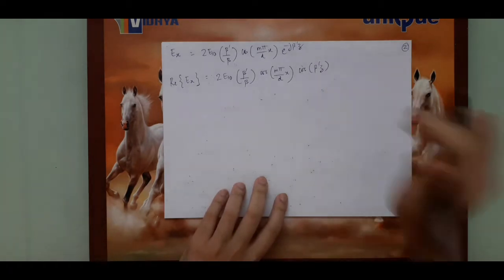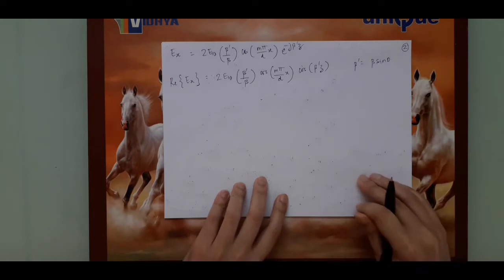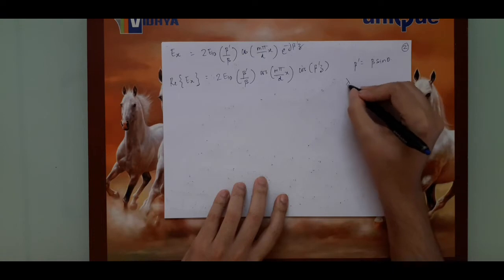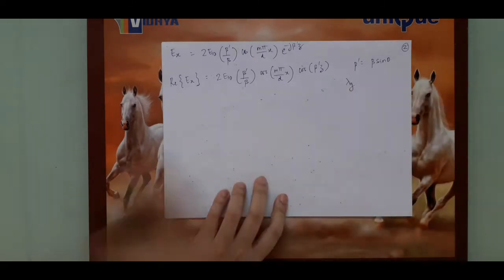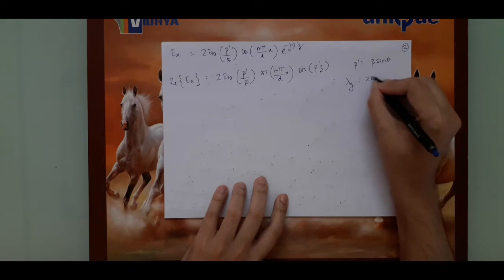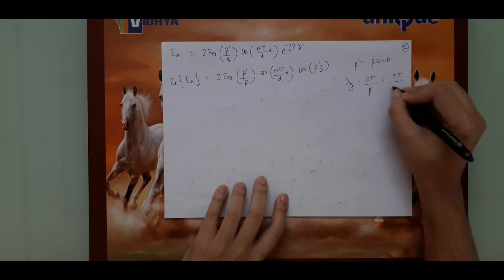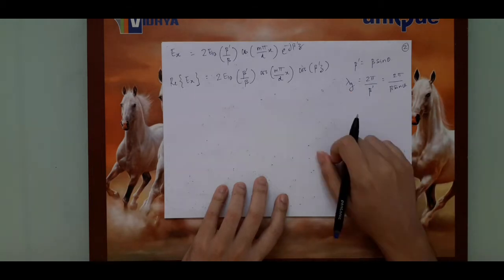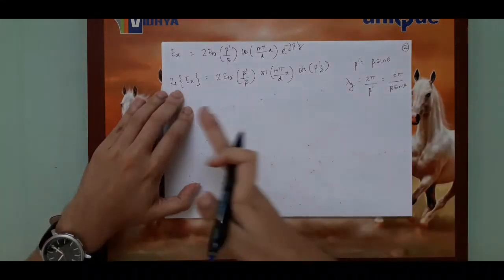Now beta prime is nothing but beta sine theta, that we know. So we can write a term called lambda g, that is nothing but the effective wavelength of the wave that is being guided along the plus z direction. This is 2 pi by beta prime, that is 2 pi by beta sine theta. The reason I am saying it in terms of lambda g is that it will be easier for us to later represent these fields as a function of distance.